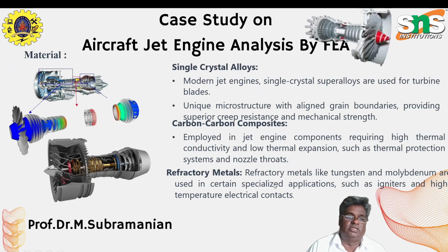Another material used in aircraft jet engine components: single crystal alloys. In modern jet engines, single crystal alloys are used for turbine blades. They have a unique microstructure with aligned grain boundaries, providing superior creep resistance and mechanical strength.